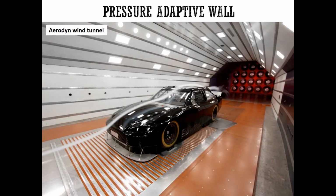Okay, some tunnels, in order to prevent this, design the test section in a way that reduces the blockage. So here is an Aerodyne wind tunnel in North Carolina, specifically designed to test cars. Now, looking at the shape of the car, they designed the test section in a way that they can minimize the blockage.